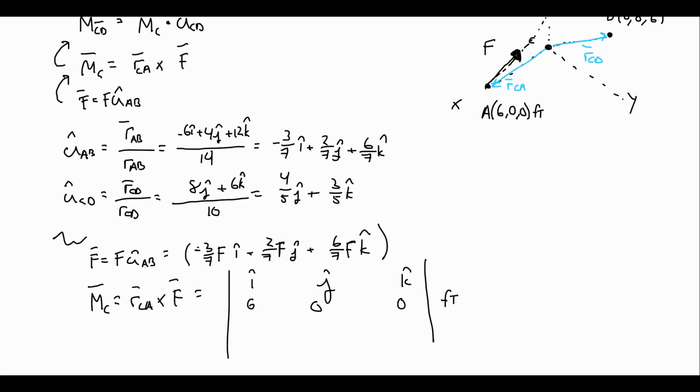And cross F. So notice here, I am keeping that unknown magnitude F in each component because it's part of this vector. It's part of the coefficient in front of i, j, and k. And this will be all in base units, so this will end up being in pounds. My F that I'll eventually find is in pounds because everything's in base units.